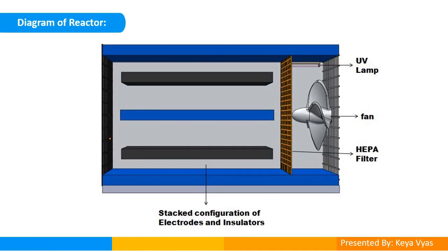So when high voltage is applied, electric breakdown leads to charging of insulating surfaces. Surface charges induce an electric field opposed to the applied field. Therefore, the total field decreases and the discharge extends. The insulator electrically acts like a load which limits the amount of charge and average current density in the gas. This keeps the plasma in the non-thermal regime.